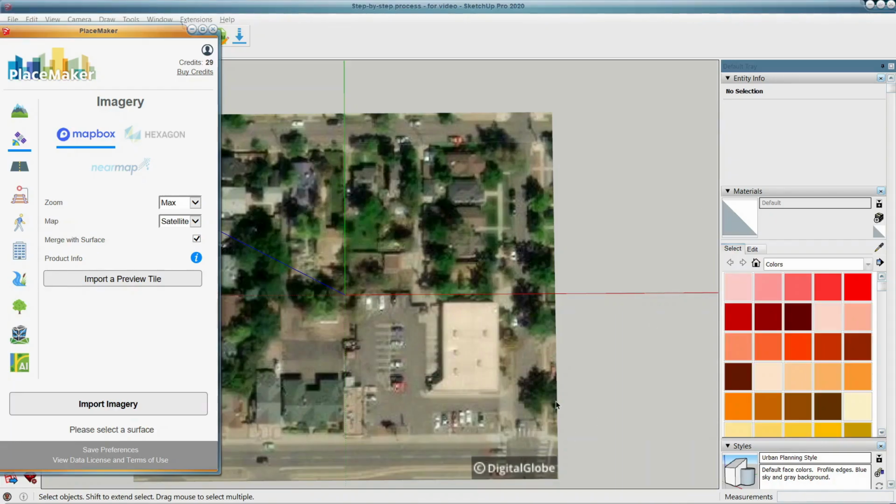And this is why I explained earlier to keep the boundary of your imported geolocation imagery tight, because the more you import, the more the credits. If you want to lower the pixelation, go to the second icon here that says Import Aerial Imagery. Also, for a heads up, importing clear imagery will often use up a lot more credits than bringing in roads, for example. So if the pixelation doesn't bother you, I won't worry about it.